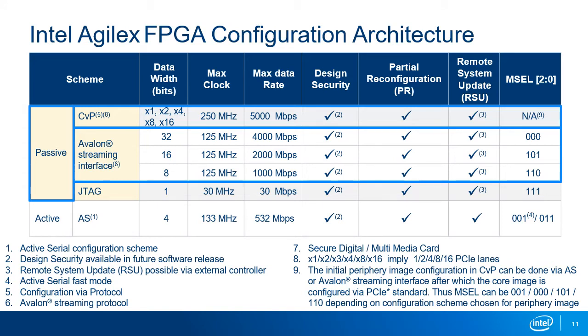The 16 and 32 modes use GPIO pins that only support the 1.2 volt I/O standard. The SDM I/O pins require a 1.8 volt power supply. Consequently, you may need a voltage level translation between the FPGA and the external host for some signals to accommodate both power requirements.